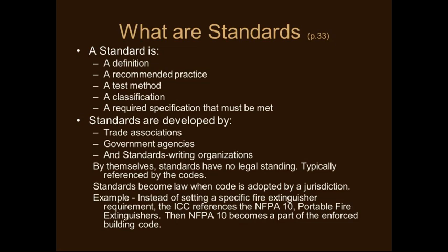Another example: instead of setting a particular fire extinguisher requirement, the ICC references NFPA 10, portable fire extinguishers. And then NFPA 10 becomes a part of the enforced building code.